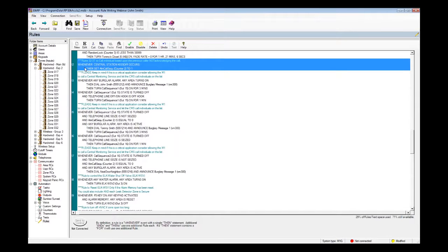If there are certain people that need to be called besides police, fire, medical, you'd want to set that up with your central station, if they do support that feature. If it's a non-mission critical, non-life emergency event and you want to be notified, the M1 has the capability of dialing a cell phone number or a next door neighbor and delivering a predefined voice message.